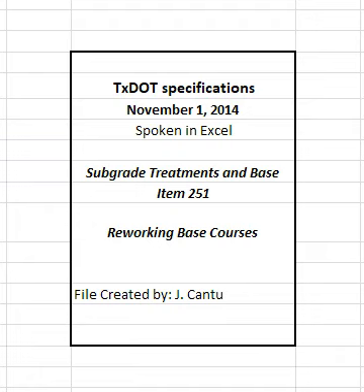3.1 Compaction equipment. Provide rollers in accordance with Item 210, rolling. Provide rollers in accordance with Item 216, proof rolling, when required. 3.2 Pulverization equipment. Provide pulverization equipment that cuts and pulverizes material uniformly to the proper depth with cutters that plane to a uniform surface over the entire width of the cut, provides a visible indication of the depth of cut at all times, and uniformly mixes the materials.